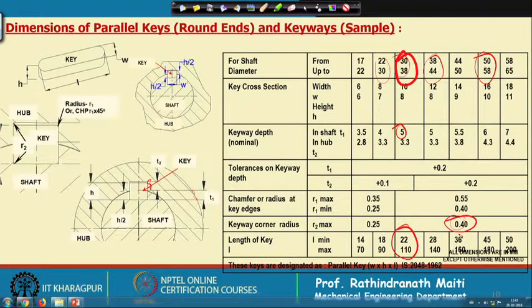So that the key can safely sit inside this, and most importantly there is a gap, this must be maintained so that there is no pressure from the top. Many people make the mistake that on the same area of the shear they consider that there will be the crushing load from the top and try to calculate, but this is not true. Crushing means the failure will be here and shear means the failure will be here.